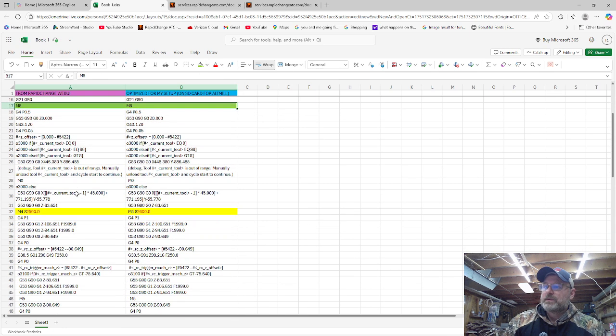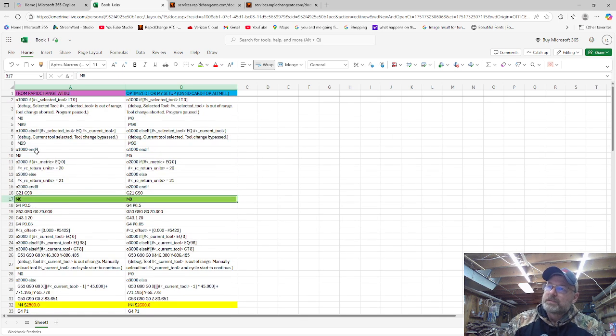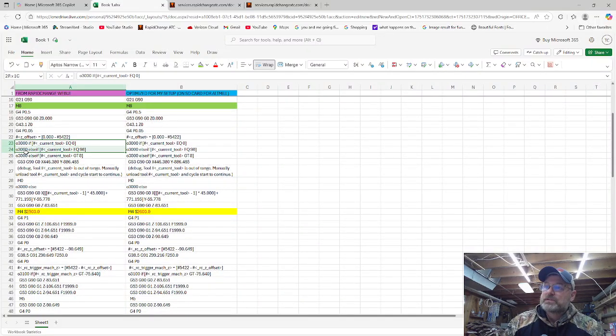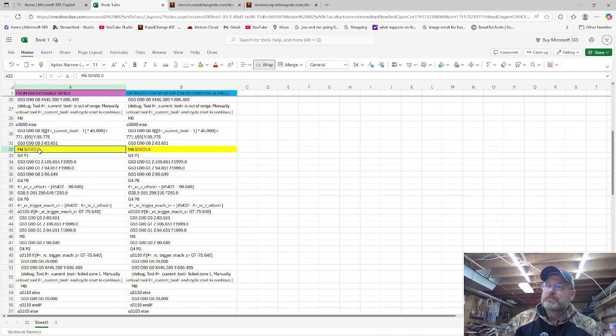And then you basically just come down here to, I guess let me give you an understanding. So you have this 1000 series numbers, this little O with 1000. You have 2000 series commands, and then you have 3000 series commands and everything underneath that. So the next one that we're going to is under the 3000 commands, and we're going to where it has an M4 command, and that M4 command is telling your spindle to turn on counterclockwise. And so this is for unloading your tool.